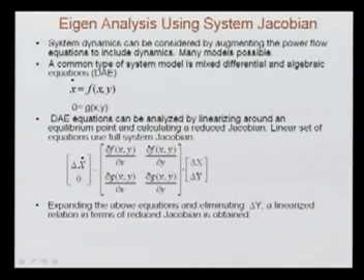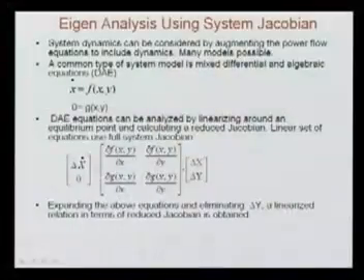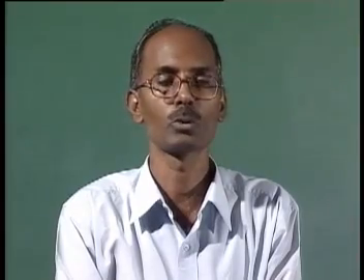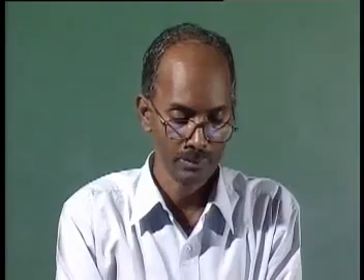Another approach, which I was explaining, is the eigenvalue analysis approach, which again comes under the repeated power flow method. In this, the system dynamics can be considered by augmenting the power flow equations to include the dynamics. The system dynamics include your generator dynamics, exciter dynamics, load dynamics, and whatever other parameters you want to include, and those device dynamics equations can be included.